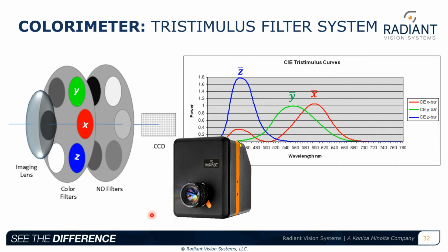So previously, when I was using these filters, we were treating them as integrals. So we basically had the spectral power distribution, and we were integrating, or shading under the curve, the light that passed through those filters. So in equipment, we're not sitting there doing integrals, we actually use physical filters. So in a colorimeter system, you actually have filters such as glass absorptive filters that let light through according to these curves. So you start by pointing your colorimeter system at the device under test, so you have all of the light coming in.